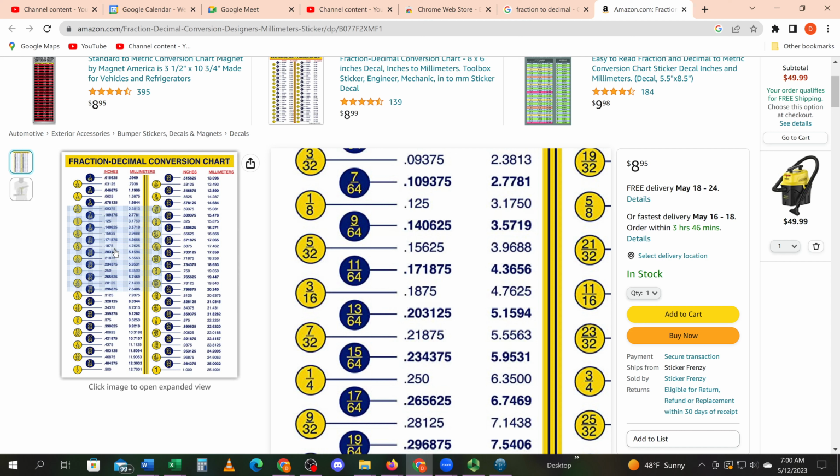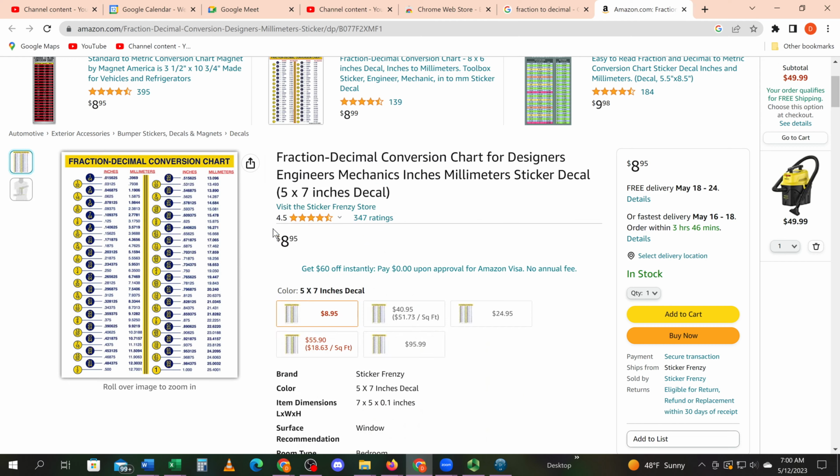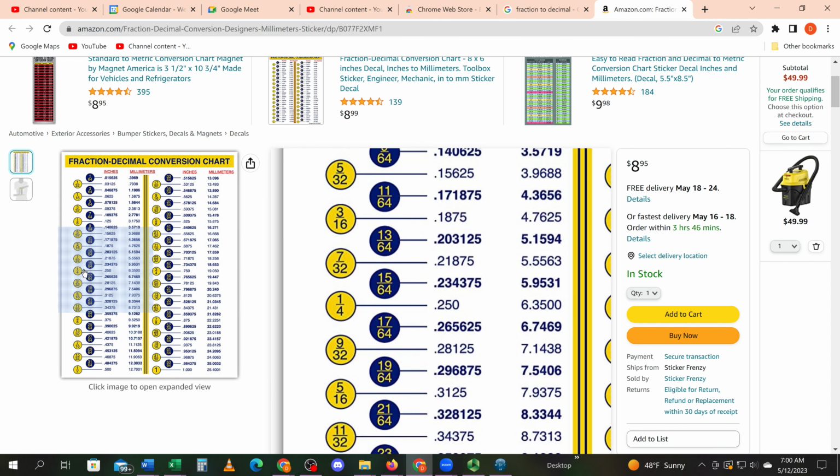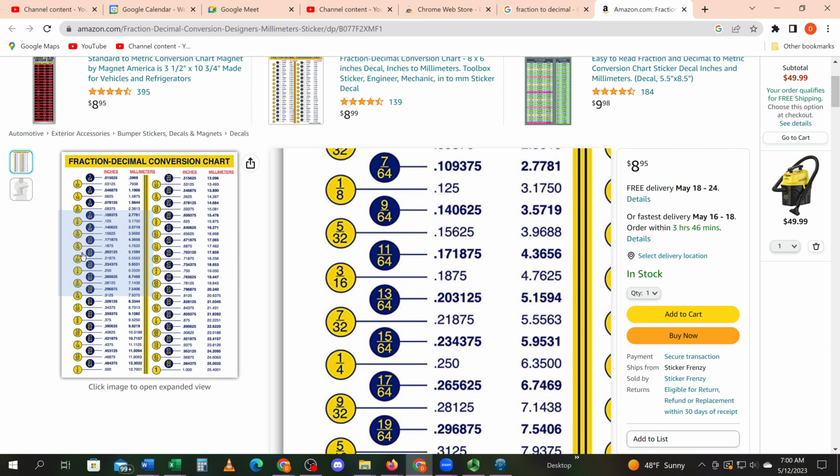Nobody says 0.00 or 0.010. Nobody says 10,000ths of an inch. We just say it's 10 thou. That is what we're working to with the 3-place dimension at 0.1875. Okay, so 3/16, 0.1875. So I know when I make the drawing, it's going to be 0.188 if I go 3 places.